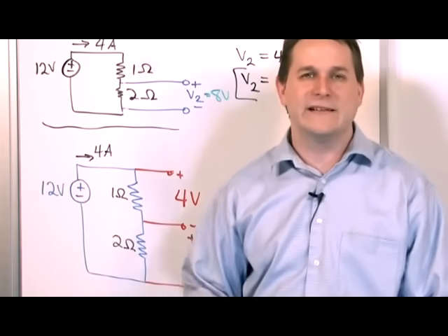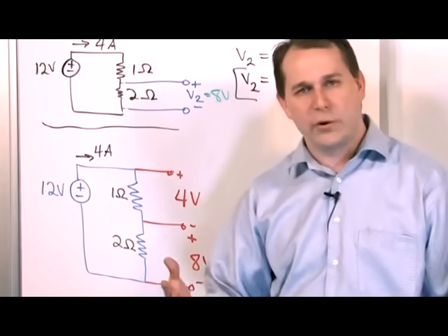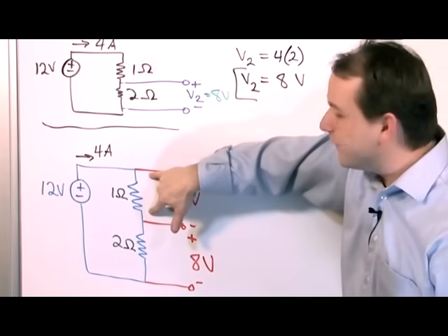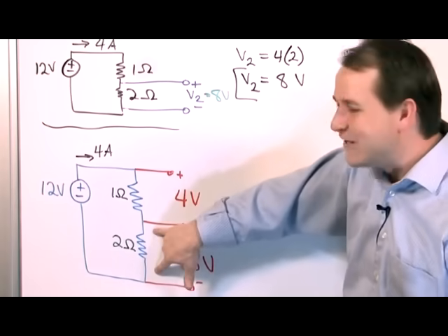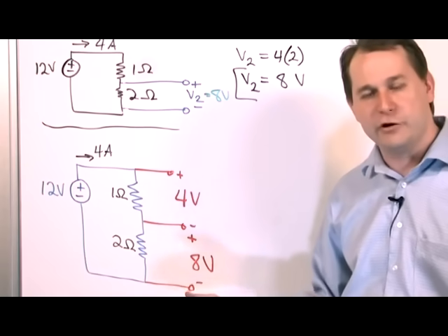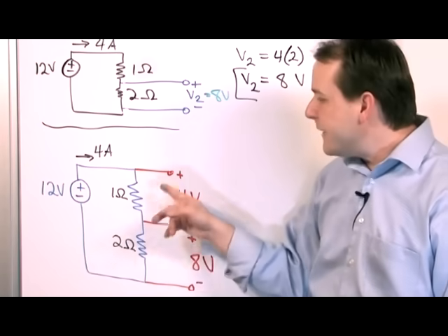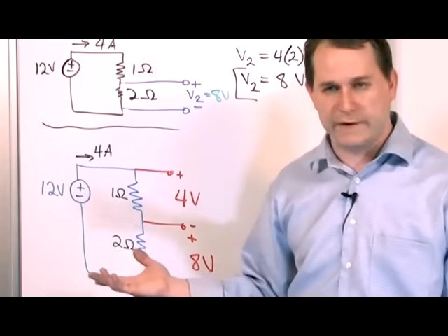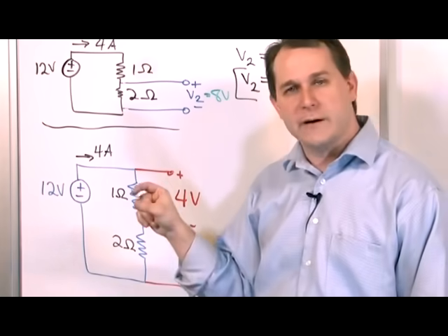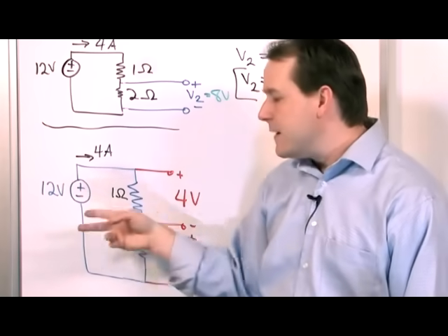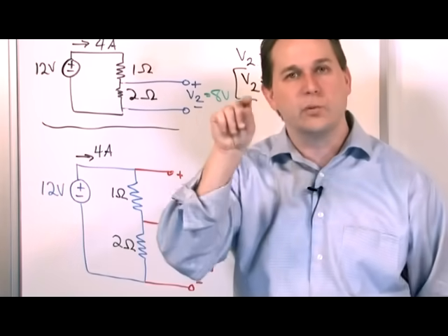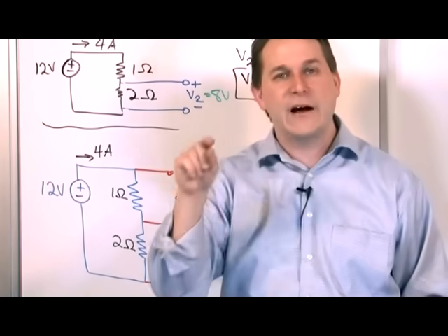That's just an analogy. It's not perfect, but it tries to get the point across that whenever you have things in series like this, you should expect to see a voltage drop here. You should expect to see another voltage drop here, but the sum of the voltages across everything should always be 12 volts. If we put 150 resistors in series and we measured the voltage across all of them, they should all add up to 12 volts. Of course, in that case, each little tiny voltage that we measure is going to be real small, right? So that you'll get different values, right?